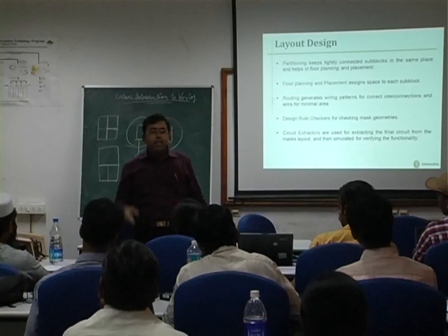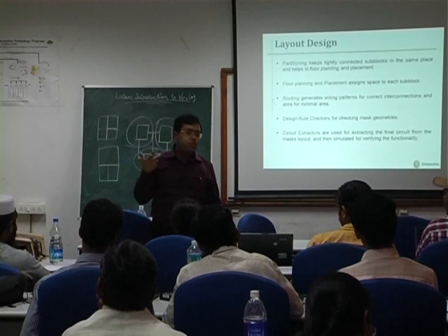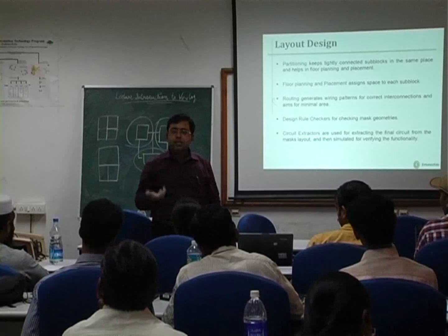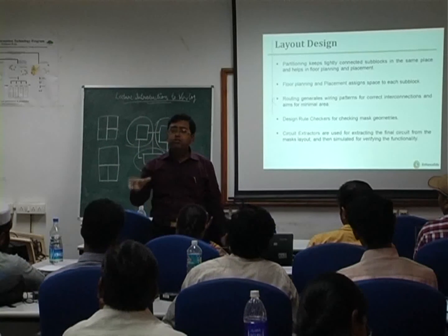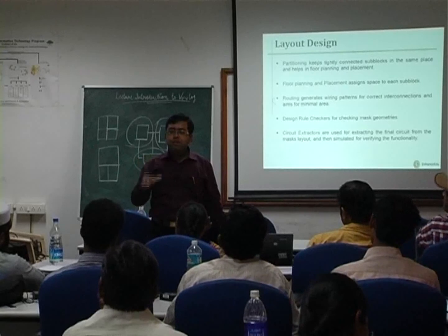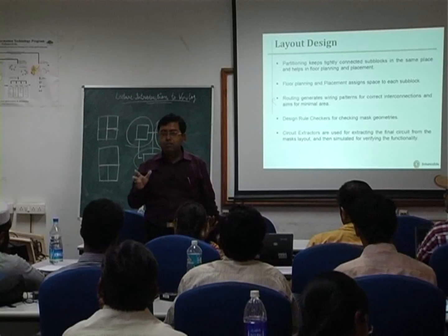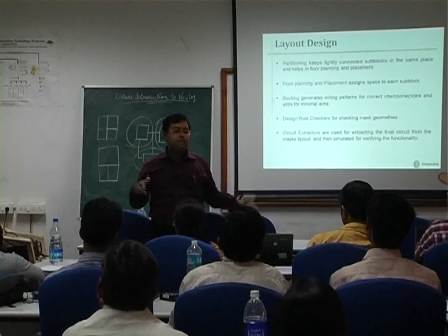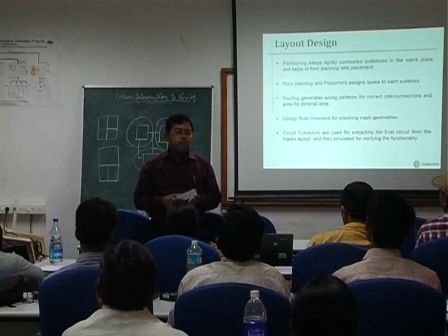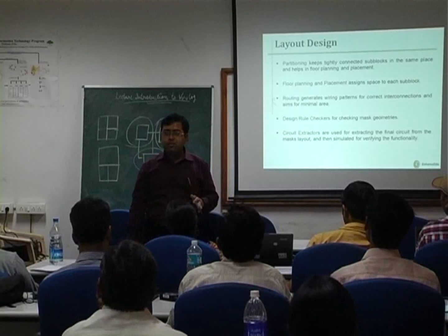So while you are designing the circuit, you may be okay with the schematic, you may be okay with the behavior of the circuit from its transistor level schematic, but once you design the layout, you may be surprised to see that the behavior of the circuit has entirely changed. When a schematic of a circuit is analyzed, the effects of these parasitic resistances and capacitances of the interconnects are not taken into consideration.